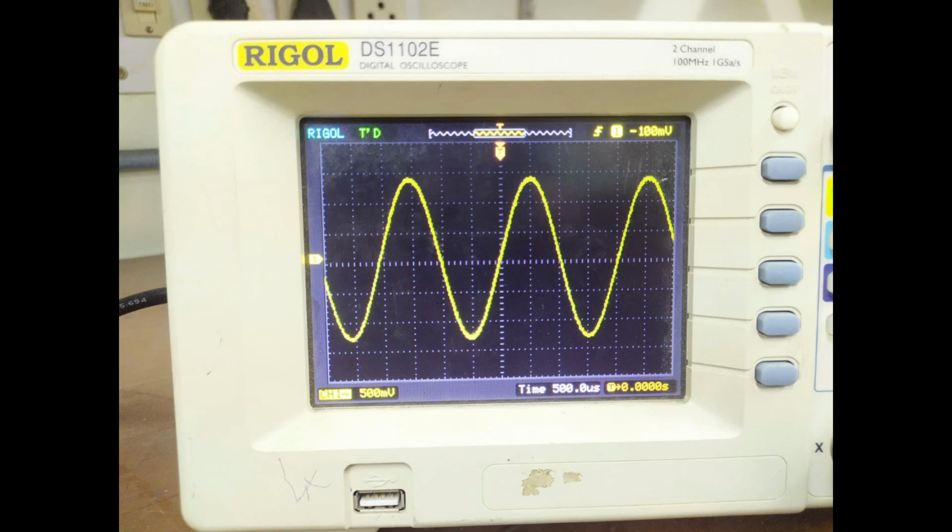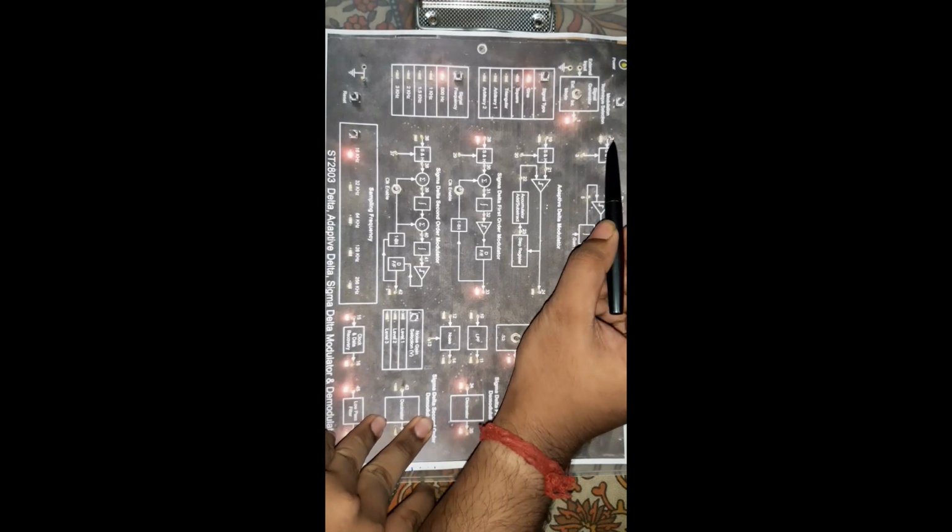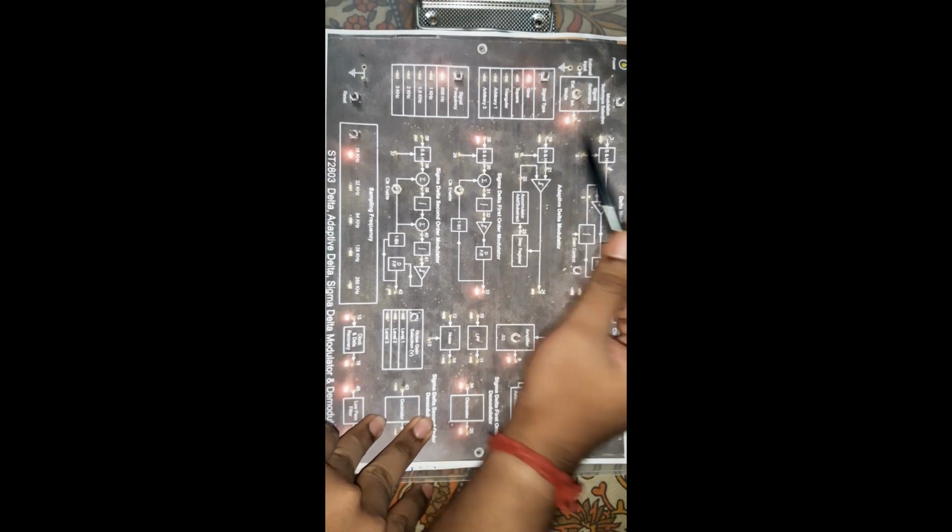I hope that you can see the input sinusoidal signal on the screen, because this picture has been captured from the DSO in the laboratory. This signal is sinusoidal in nature, and the 500 Hz frequency can be clearly calculated using the time divisions, a basic calculation actually. So you can see the sinusoidal signal of 500 Hz frequency has been fed to all of the inputs of the sample and hold circuit.